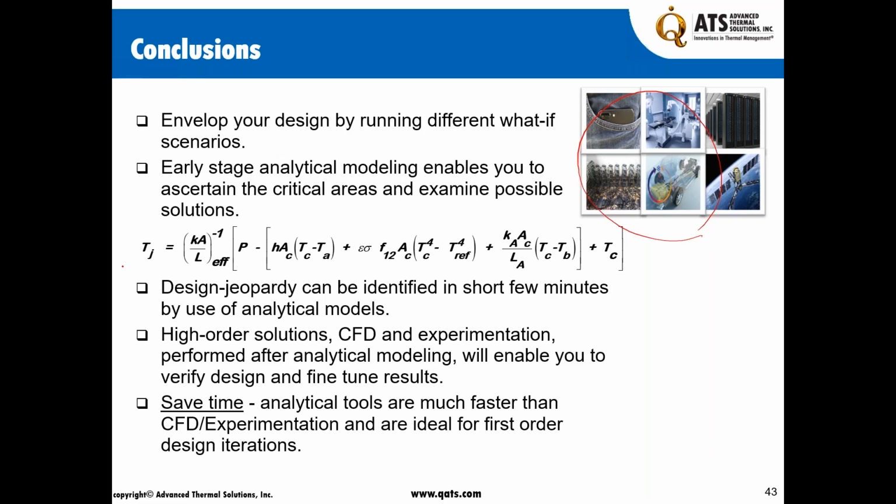So right here, from the analytical model that you're putting in your Excel spreadsheet or whatever model that you have, you can go in there and change these parameters and develop a variety of design curves for junction temperature as a function of velocity, junction temperature rise as a function of board conductivity, as a function of neighboring boards' power. Just name it.